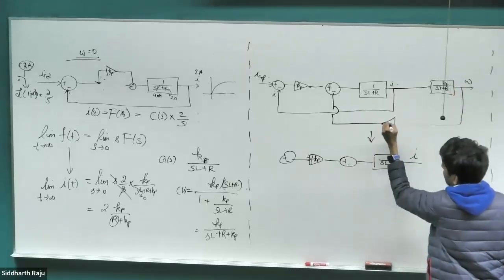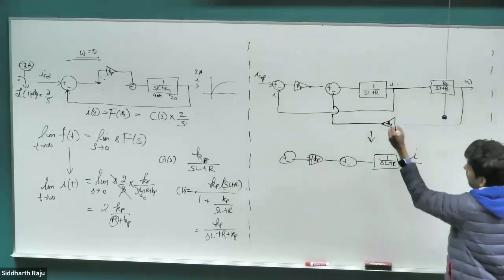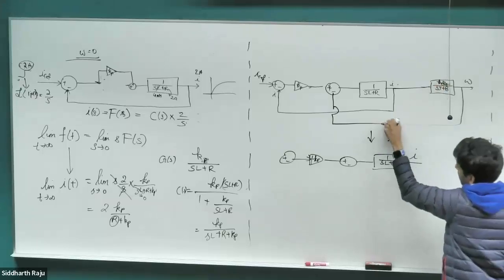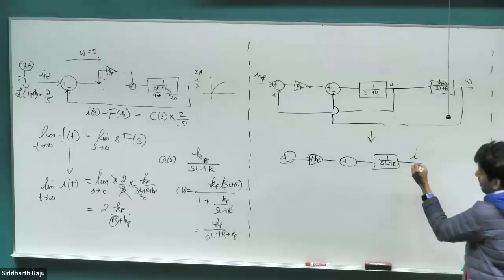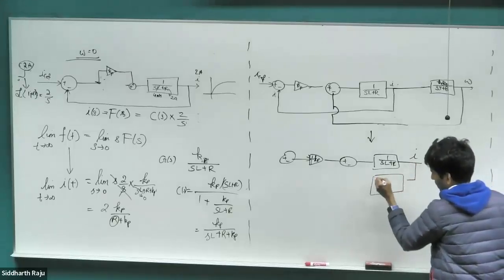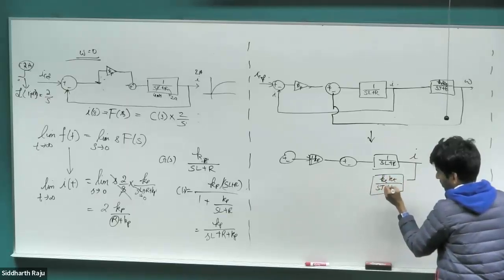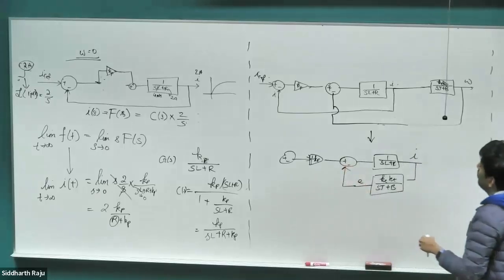Oh, there's a Ke term, sorry. Right? Comes back as a Ke term. So let me take this Ke and move it here as well. So I have Ke Kt divided by Sj plus B. Right? And now what I have remaining is the same current term getting multiplied by Ke Kt over Sj plus B, giving the EMF in the end and closing the loop.